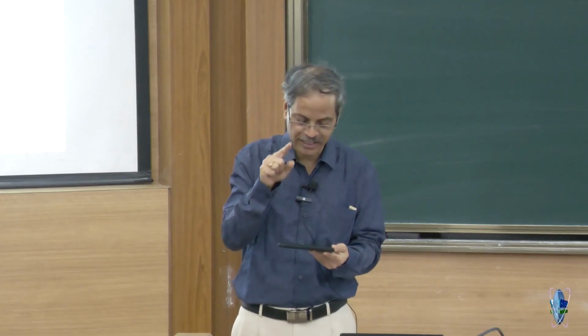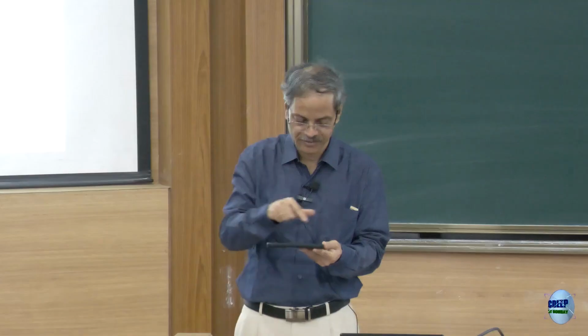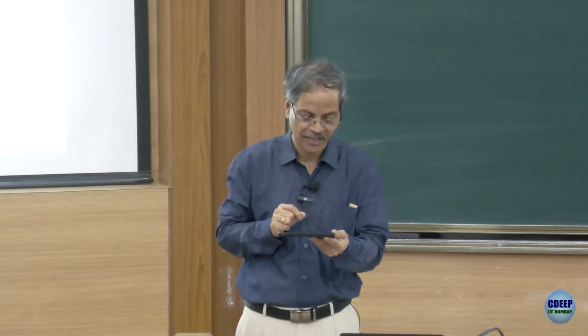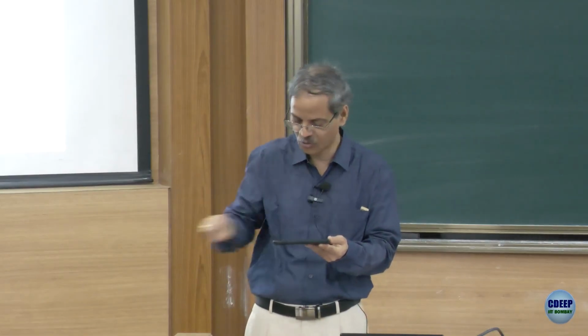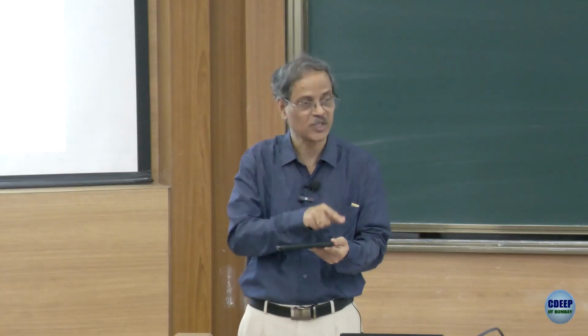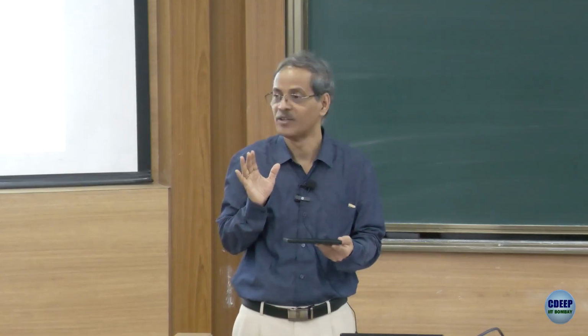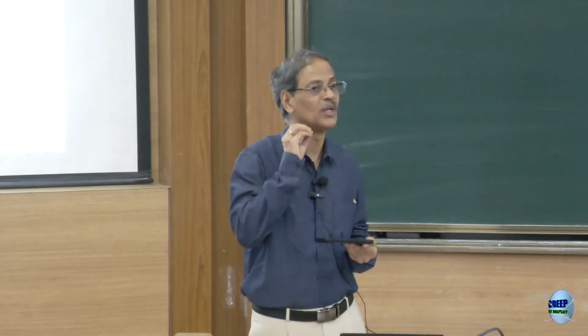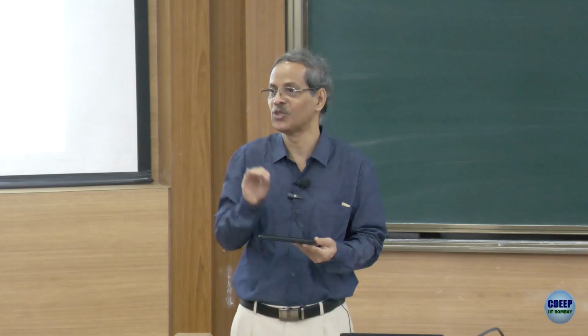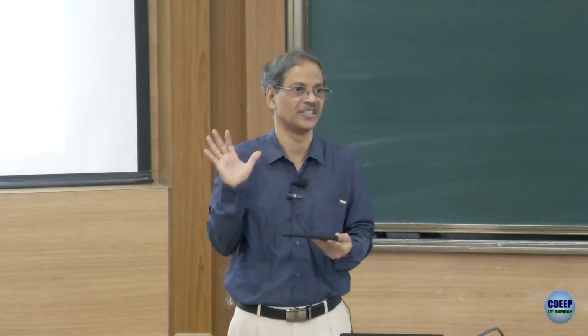So, I am taking a triangle. So, 3 vertices, each vertex will have u displacement, v displacement, u, v, u, v. So, 6 displacements, okay, which are unknowns for that element. So, therefore, I am going to end up with how many equations? For this element, I should end up with 6 equations.